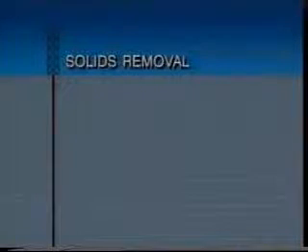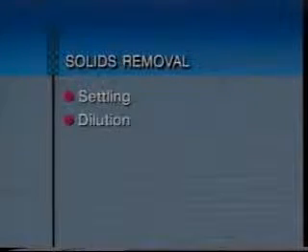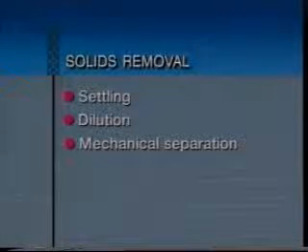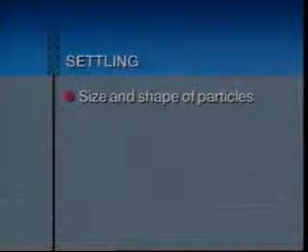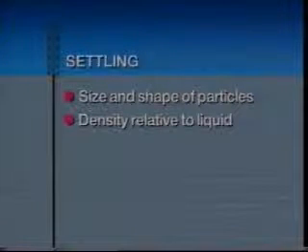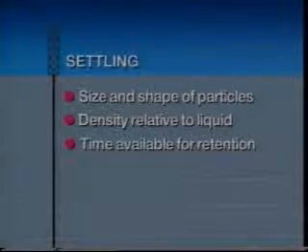The removal of solids can involve any or all of 4 treatment techniques: settling, dilution, mechanical separation, or chemical treatment. Settling is accomplished by allowing the drilling fluid to remain in a near quiescent state for a time period long enough to permit the heavier particles to settle out. The success of this technique depends on the size and shape of the particles, their density relative to the fluid's density, and the overall retention time.